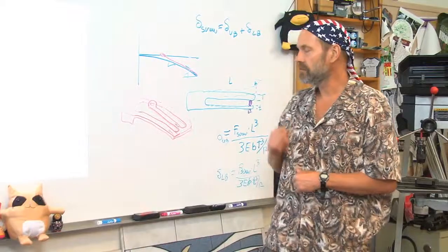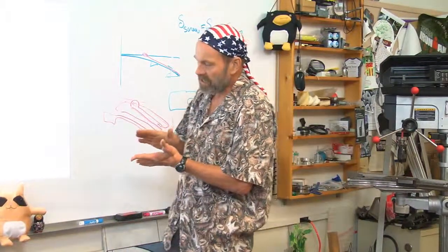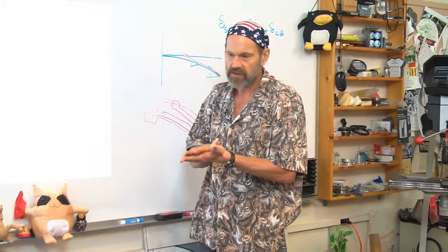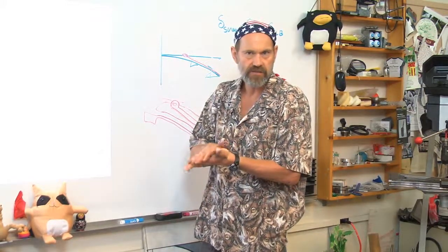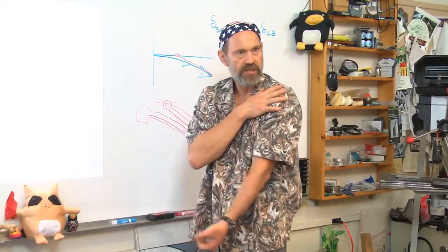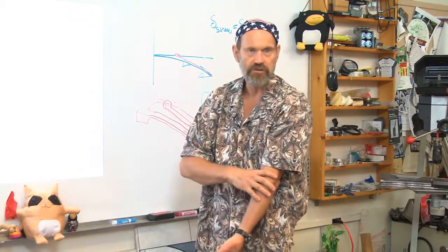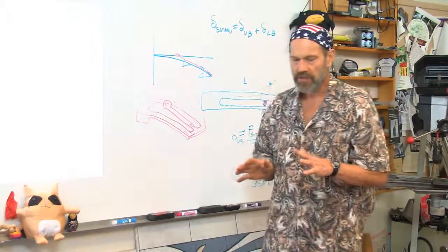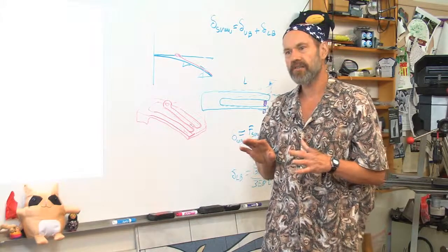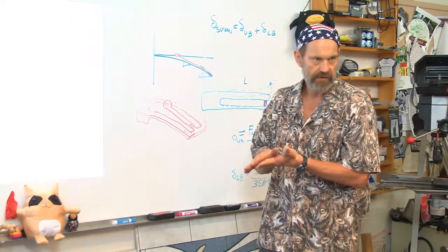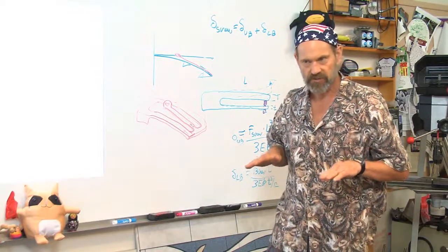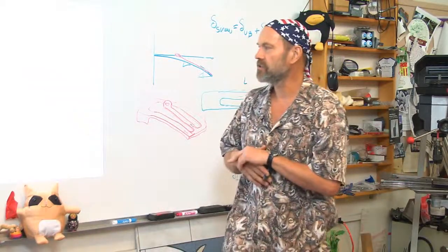Speaking of knees, what type of lubrication do you have in your joints? We just said that, for example, in your knee joint, you've got sliding contact. And in your shoulder joint, for example, any of your human joints, you've got sliding motion. The speed is very low, so that sliding motion tends to be what's called a boundary layer. You never build up a hydrodynamic wedge, which is what happens when you start sliding on the beach.